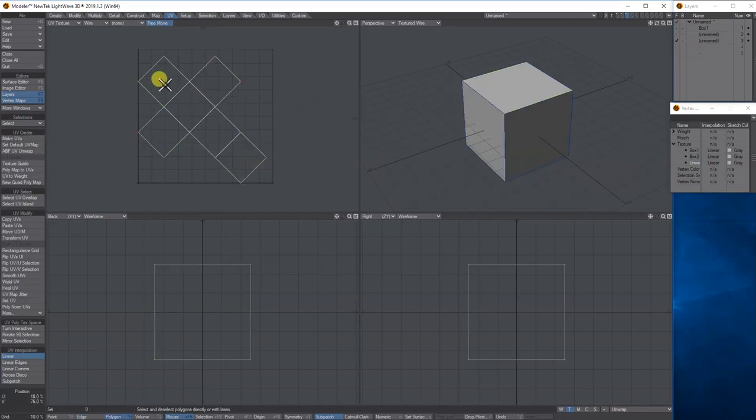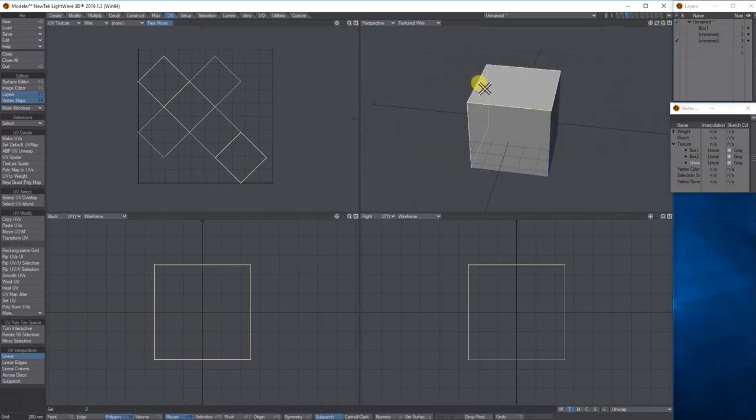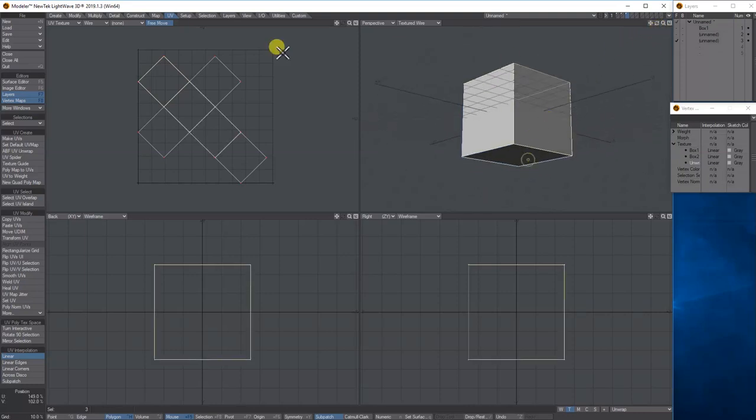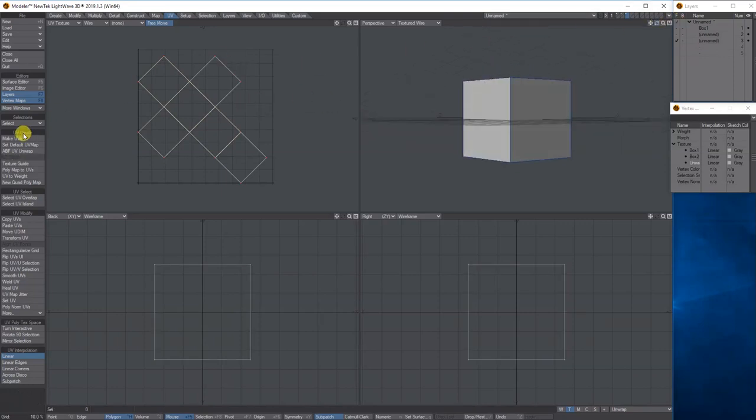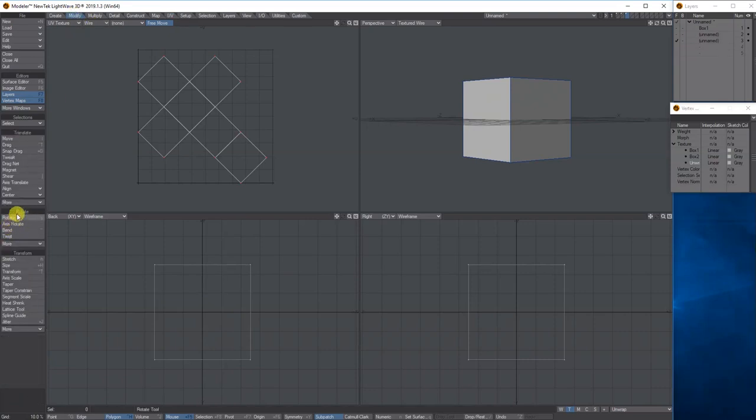So what I mean by that is it goes in sequence. So imagine the box is being unwrapped, so it's unwrapped there, and there's the side bits, look here, being unwrapped. So again, another really easy way to do it with the ABF unwrap. What I'm going to do is rotate it, just size it a bit so it's just inside like so, and then adjust the rotation so it's better like that, and then what I can do now is take this through like before.